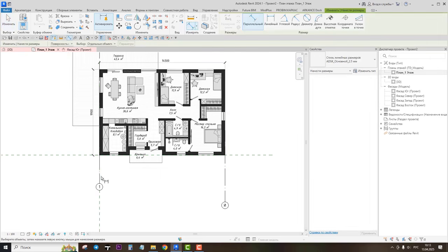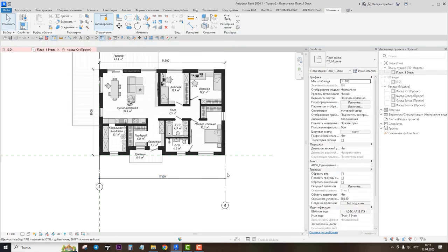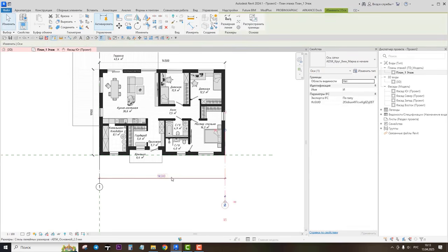Or you can use constant dimensions. Choose the tool measure, aligned dimension for example. Measure this dimension from these two lines. Select the line, change the dimension, and the line is moving. Remember, the element I'm selecting is the one that moves when you change dimensions. So you can use temporary dimensions to position the element faster, or you can use constant dimensions, change these dimensions, and the element is moving.